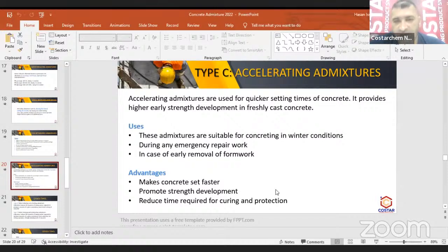So they say, for instance, that if my compressive strength, my readings for my cube crushings, is at 65%, then I pass, and I'm entitled to get paid. That's the meaning of it, all right? So where did the 28 days come from? Well, in Europe, they don't get paid on a weekly basis. Basically, it's on a monthly basis, and the month is 4 weeks, so 7 times 4 gives you your 28 days. As you can see, crazy, huh?